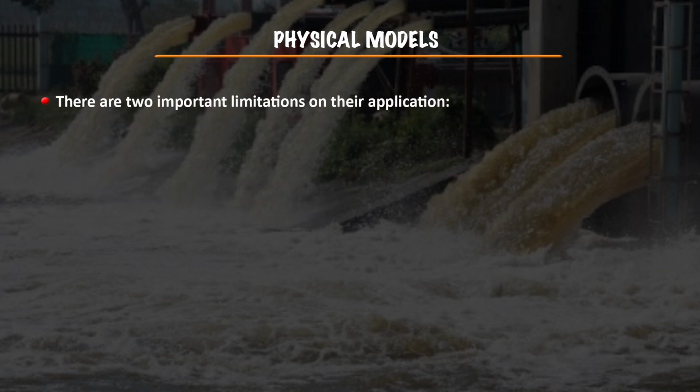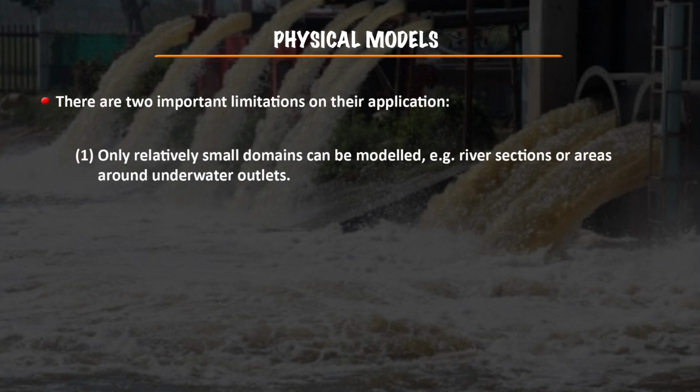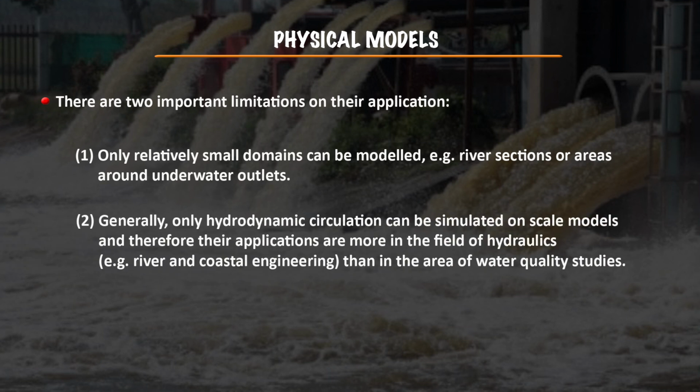There are two important limitations on their application. One is that only comparatively small domains can be modeled, for example river sections or the areas around underwater outlets. The second is that generally only hydrodynamic circulation can be simulated on scale models, and therefore their applications are more in the field of hydraulics, that is river and coastal engineering, than in the area of water quality